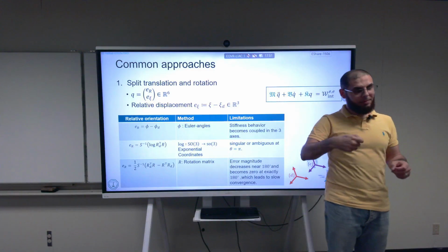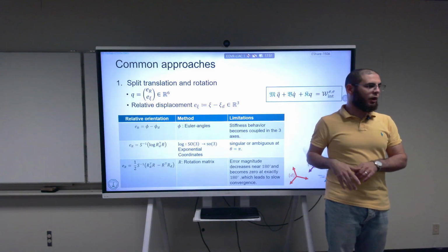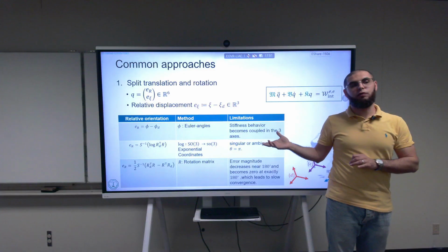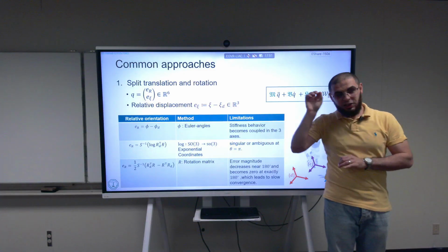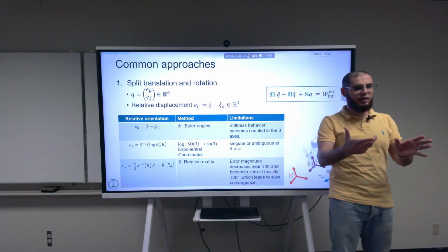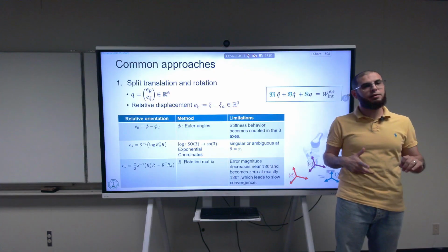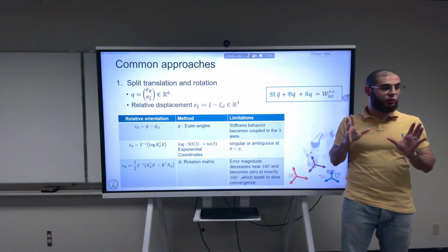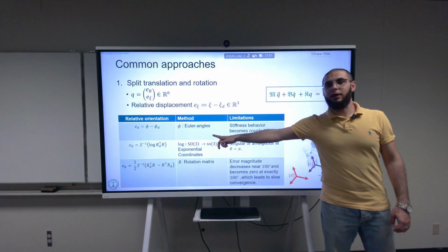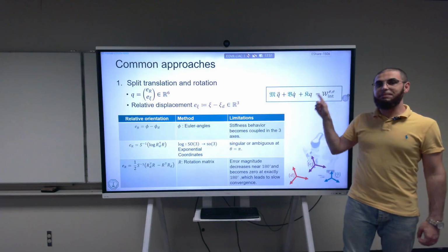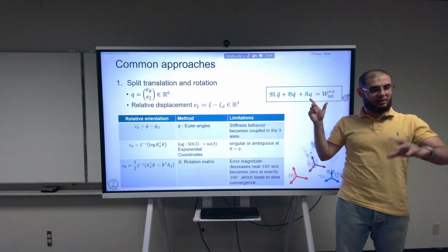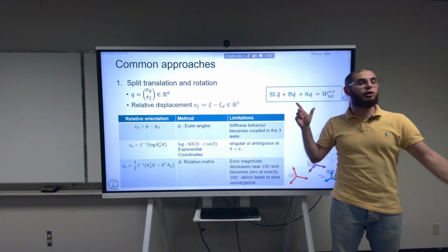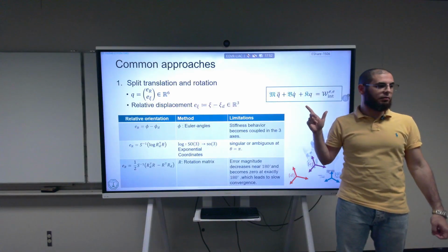Now, you can actually show it in math, and I'll give you some reading material that you can read on your own. There's a very nice chapter in the handbook of robotics on force control, and they discuss exactly that point. They even derive it, and it's very easy, very simple math. It's very non-intuitive, but when we use Euler angles, the true stiffness matrix that represents the spring on SE3 depends on the orientation you're at.